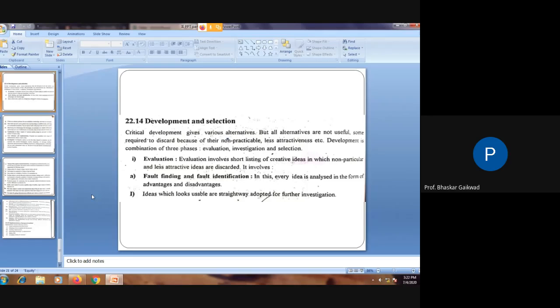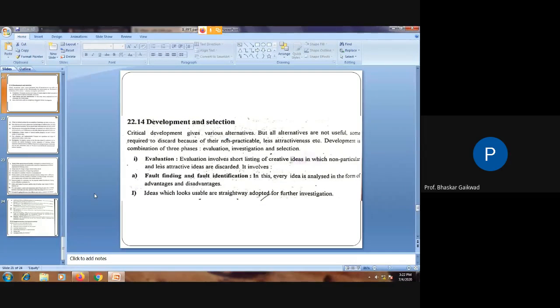If you have selected press machines to manufacture the washer, what are the advantages and what are the disadvantages? If you selected a forging method for manufacturing the washer, what are the advantages and disadvantages? For forging, we require heating devices, so this is a disadvantage and a cost. And after forging, according to the purpose of the washer, whether these recrystallization parts are actually required in the assembly or not, this also we can discuss.